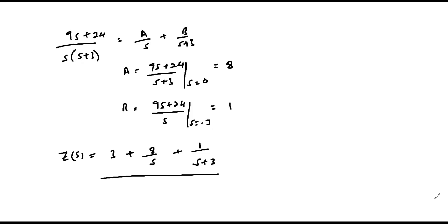Next, we proceed to implement our transfer function using the 4 methods: the Foster series, Foster parallel, Cauer, and Cauer canonical forms. The first one is the Foster series. In the Foster series, as we saw in the LC networks, all the components are in series, and if there is any arrangement in parallel, it is in series with the entire network.